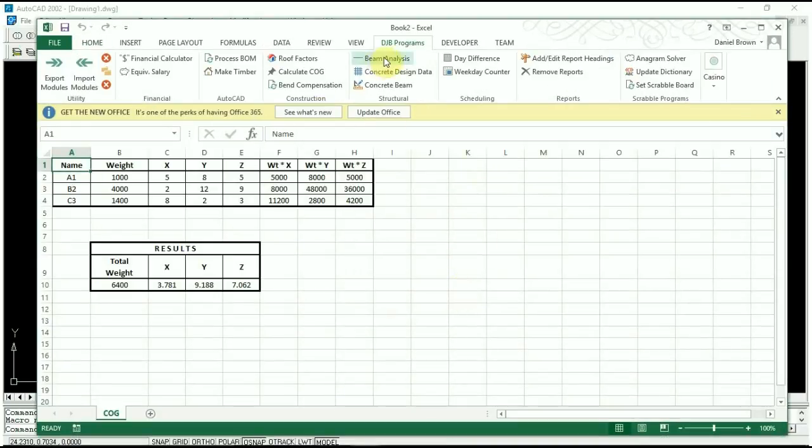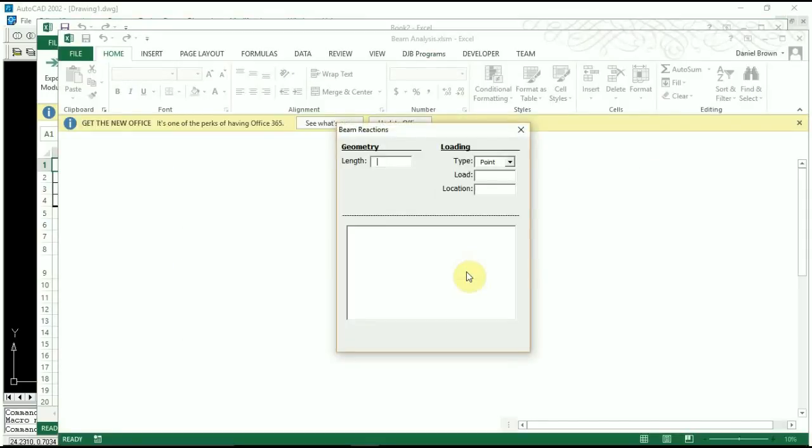Okay, now I've got a beam analysis program, which is for continuous beams that are statically indeterminate up to 3 degrees of indeterminacy. This would be for designing concrete slabs or concrete beams because they can be poured monolithically. For steel and timber, typically they're statically determinate for regular gravity beams, for constructability purposes. Typically, I never went over 3 columns, so I didn't even have 1 degree. But if I did, those are simple enough to do by hand. You can just do virtual work, and that's what this does. It does virtual work up to 3 degrees of indeterminacy.